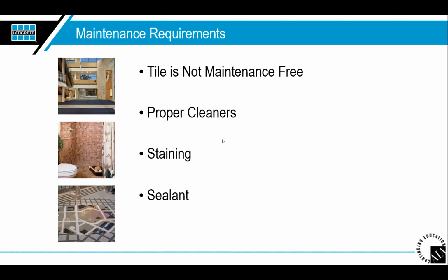Yeah, what are you recommending to clean the floor? Just plain water, or water with vinegar? No, I don't recommend vinegar at all. I know people that have stated that in the past. I'm a big fan of just neutral pH cleaners, right? It'll say that on the bottles. So don't use Windex, not using bleach, not using vinegar, that kind of thing. But yeah, a neutral pH cleaner, something that's non-acidic.